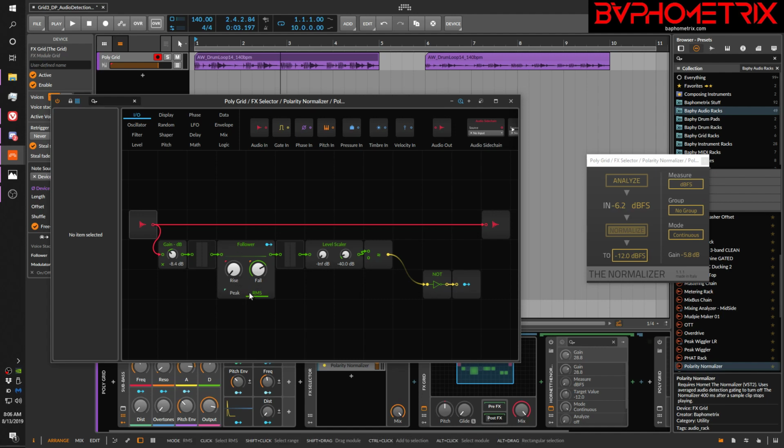You'll also notice that in this one, I used the RMS value instead of the peak value to be the thing that's normalized. I don't want every one of these transient peaks to be the thing that I'm normalizing and averaging, if you will. I want the overall energy, the RMS, the non-peaky stuff. So I'm taking the non-peak stuff and really pushing up the follower's fall time. And I have to do that to keep this line up above 0 long enough to keep this smooth and steady.